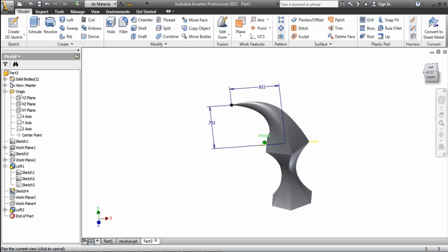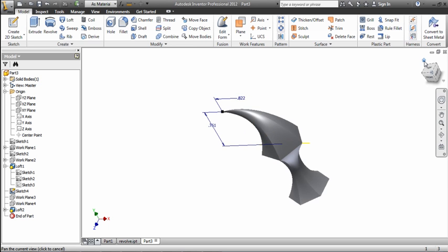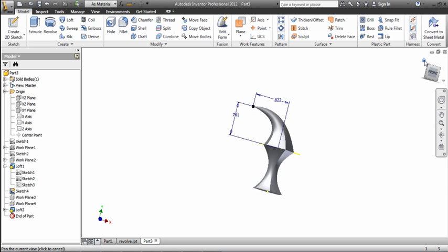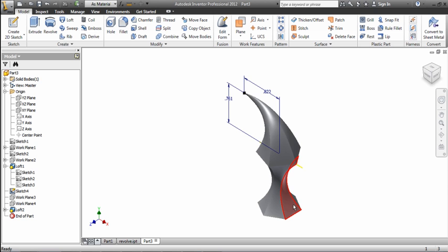But anyway, you can make so many different things with a loft. It does take a little bit of artistic creativity to think through how you can use the loft tool, but you can use the loft to create some very interesting shapes. You just don't want them to run into each other while they're turning. You want to have plenty of space for them to stretch out and be creative. Sometimes lofts won't work the way that you want them to. If they don't work, then you probably have to edit one of the sketches or make the sketches further apart or closer together, depending. So it's very difficult to show all the different issues that you could have with a loft, but as you start creating them, you will become better at them.